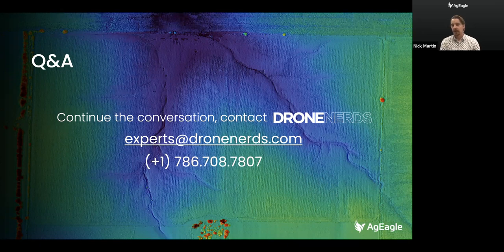If people out there fly DJI drones and are interested in hooking up a MicaSense camera to it, get the Skyport additional piece. It will allow you to write RTK data onto that TIFF image. And when you have extremely precise location data, photogrammetry engines will usually produce much cleaner maps.